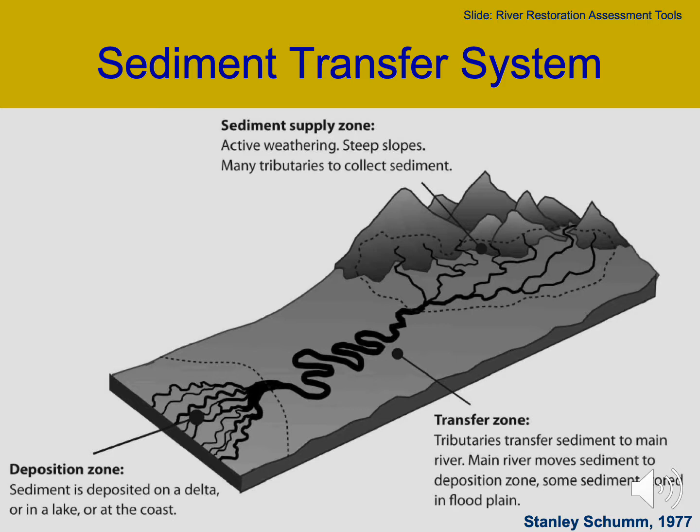If you put a boulder weir system in here, you're going to probably do well in maintaining your pool scour depth, but you're also going to struggle to keep your boulder weirs in place over the long term. Here we have high sediment transport capacity, so the river channels can continually mine the bed of sediment, often plucking some of your rocks that are holding your boulder weirs in place. Down here in a sediment depositional zone, your boulder weirs are probably going to have a much longer life, longevity, but again, they're going to fill up with sediment, and pools are your main objective here.